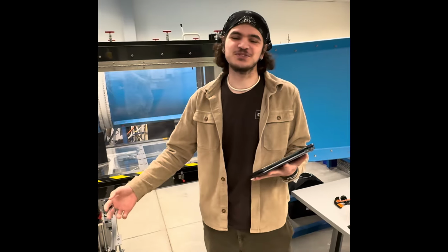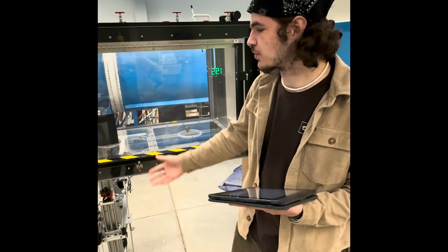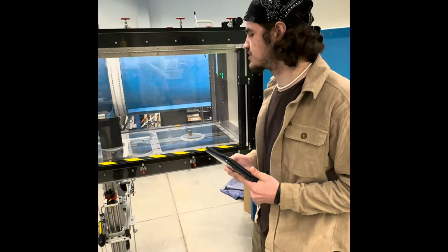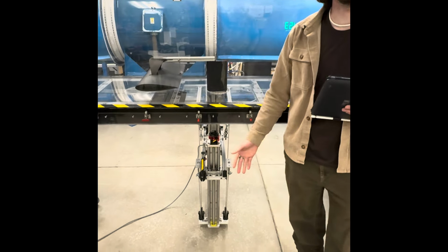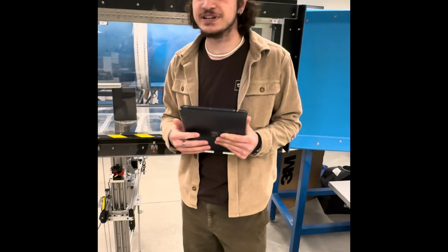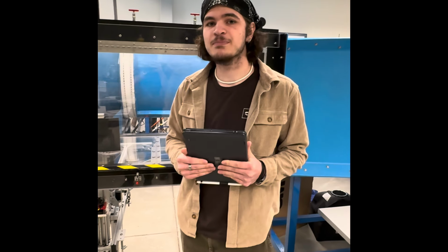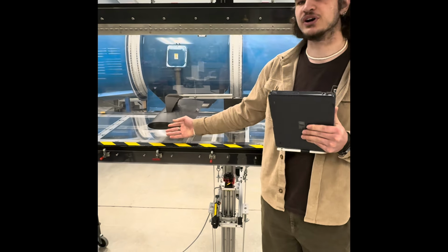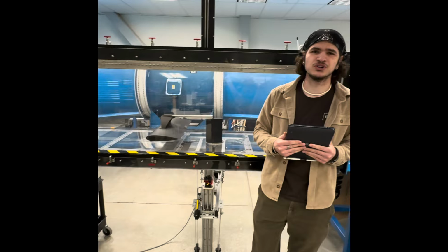Perfect. So some variables that we're going to have are a lift force, a drag force, and we're also going to be measuring the chord length. With this, we will have some sources of error, and one of those places is going to be coming from the load cell. However, we do have the uncertainties from different data tables in regards to that. Another area where we might face some error is the angle of attack on our airfoil, which will give us plus or minus 1 or 2 degrees.